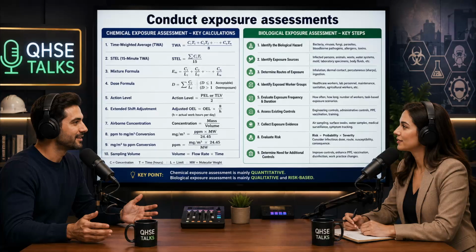The sources also note that this principle of proportionality isn't just for human toxicity. It's used for physical hazard assessments, too. Like flammability. Exactly, estimating the lower flammable limit, or LFL, of a mixture. If you have a paint stripper composed of 15% acetone, 20% toluene, 30% methanol, and 35% dichloromethane, you use proportional math to find the composite flammability risk of the vapor cloud. The exam frequently tests the LFL mixture calculation to ensure you understand that physical hazards compound in the exact same additive way that toxicological hazards do.